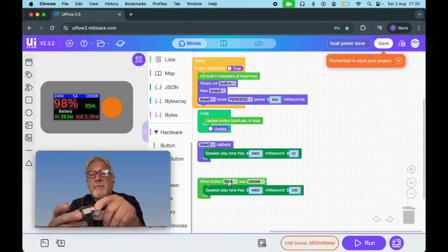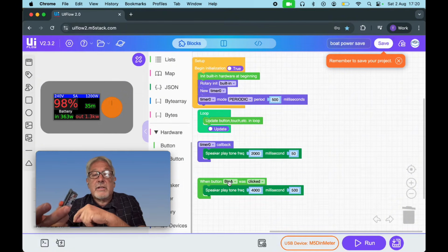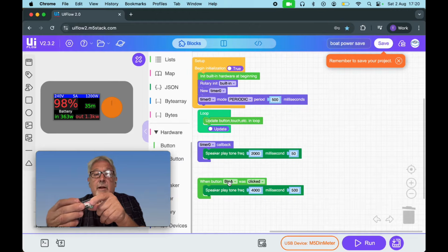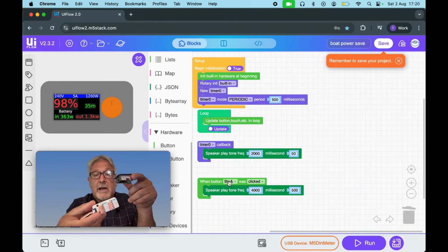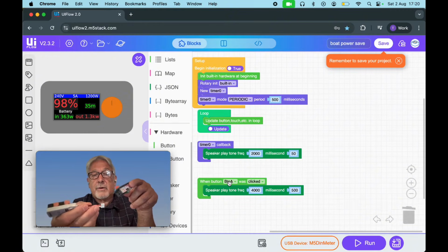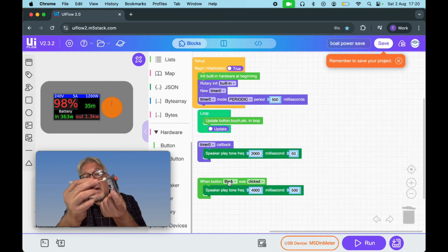If I have these running and there's no connection to the Raspberry Pi, because the Raspberry Pi is off, then these will work in local mode. They'll run the timer in local mode and just control the local switch. To do that, I'm going to fit some relays. These are 2 relays, again plugged into a Grove connector, which will plug into the back of this.